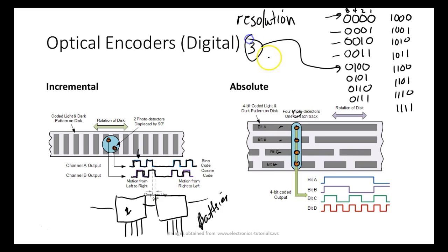It would look at this and convert it over to a binary number that represents that. And then we would scale it according to what we needed, right? You understand? So now we would have to say, okay, a count of 4 equals 6 inches. And that's what we call scaling. In sensors, we'll call it a transfer function, because that's the way I learned it.